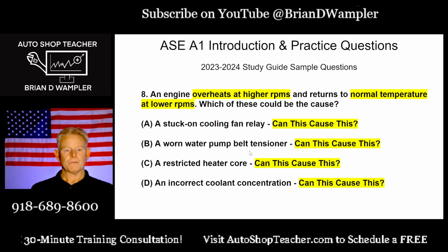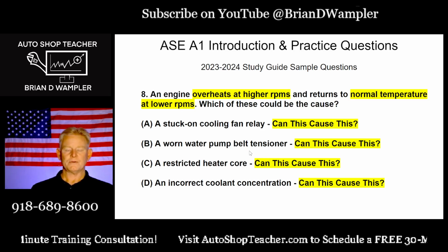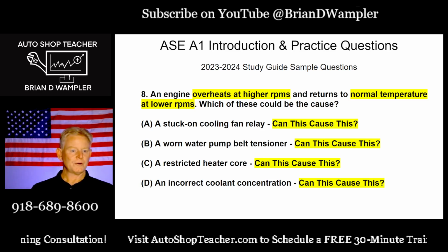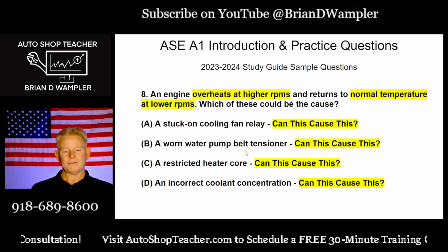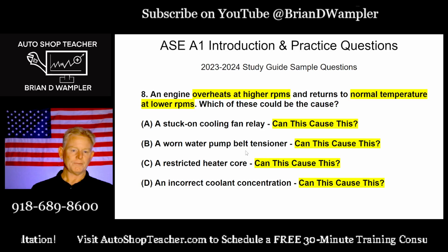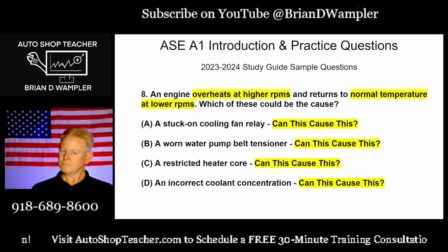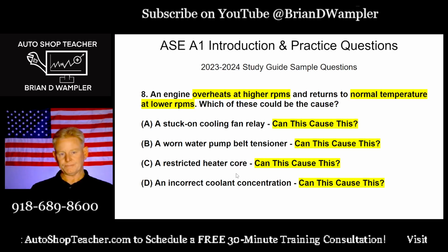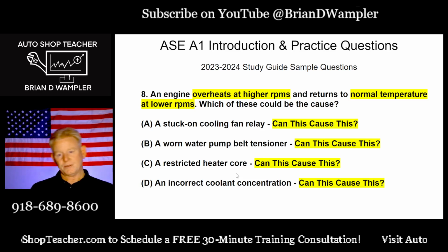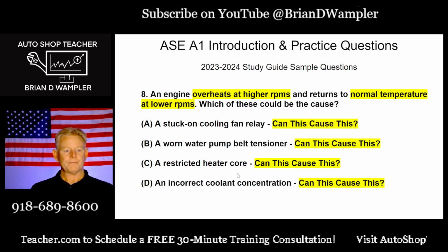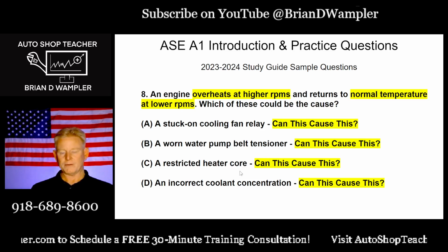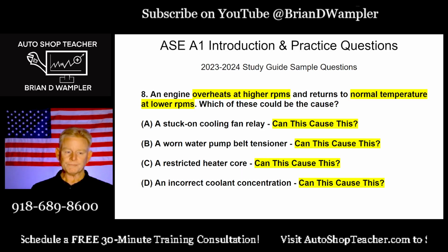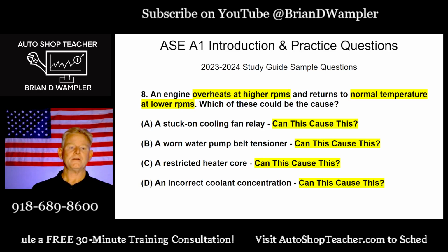Well, when the engine's at slower speeds, it's okay, but then at high engine RPM, if that belt tensioner is bad, could possibly the belt be slipping for the water pump? Think on that. Restricted heater core. None of the information given to us in the question is talking anything about HVAC. By that I mean heating, ventilation, and air conditioning. So is the heater core even really a play in this?